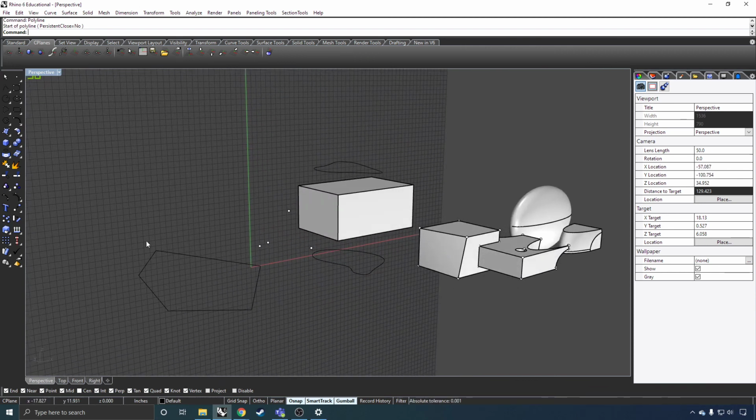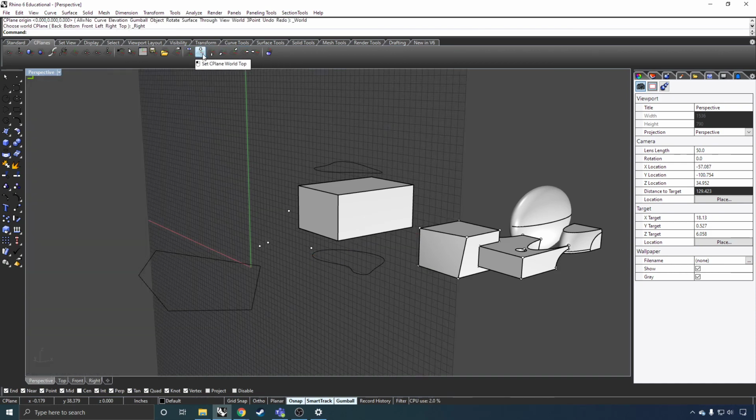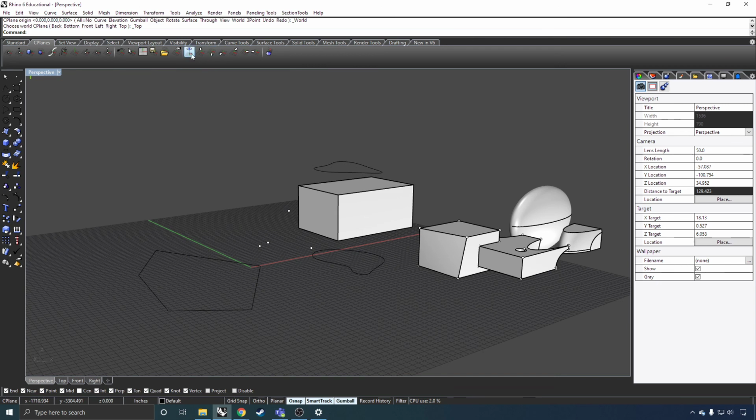It trips me out a little bit whenever I change this, but in some circumstances, working in elevation is much more useful, like when you do furniture profiles. Same thing if you go from the right or the other side. Just know that you can reset stuff here. You can also do much more custom things where your Z axis is slightly off. I wouldn't recommend doing that often, but if you, for some reason, mess up your C-plane, this is the button to remember. C-plane to world top.